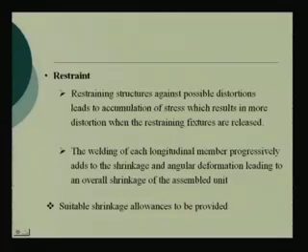One of the traditional things, I just mentioned in the beginning, is that people realize that distortion will take place. Why? Because it is a thermal process. So, what to do? You will have to live with it. Another is restraint. If you go to the shipyards, when the panels are being fabricated, you will find big huge concrete blocks kept, the stiffeners are there in between, and welding is being done. So, what happens? It is being restrained from deformations.